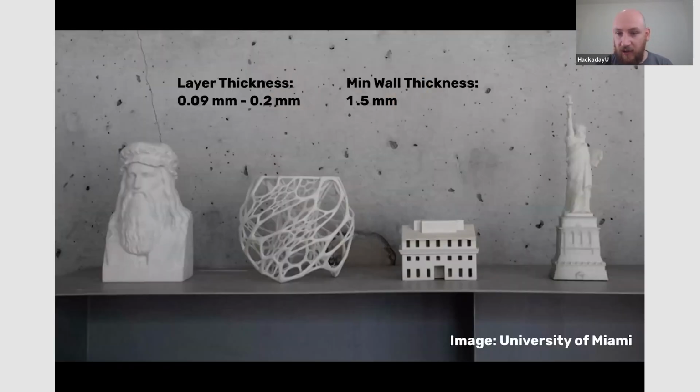These are some examples of 3D models made with Z-Corp 3D prints. They generally have a thicker wall thickness and are more fragile. You don't want too much glue, because the more glue you put on these models, the stronger they will be, but it gets a bit tacky looking. So you want a happy medium. But if you don't put enough on, they crumble. So they have a shorter lifespan than a plastic model, where you're not going to have many problems long term.